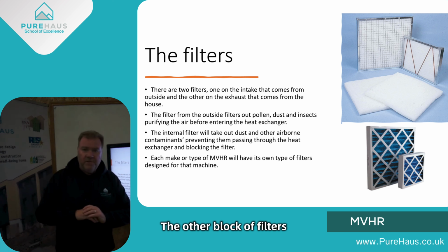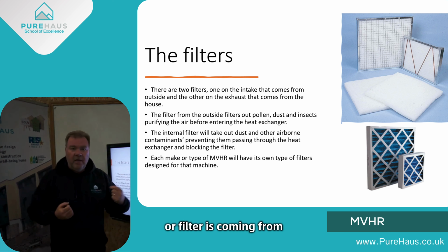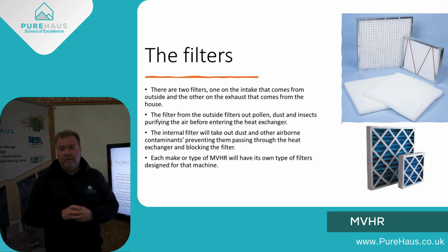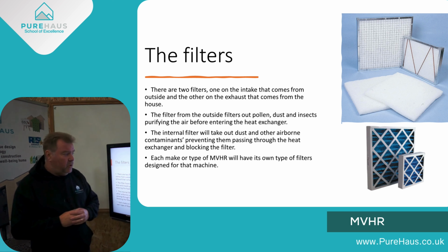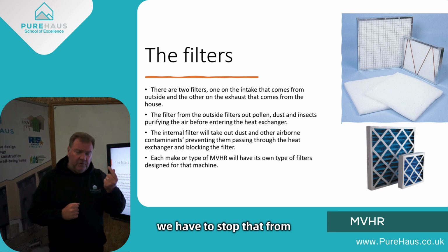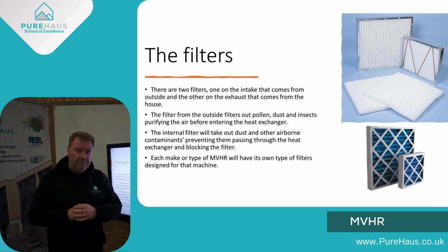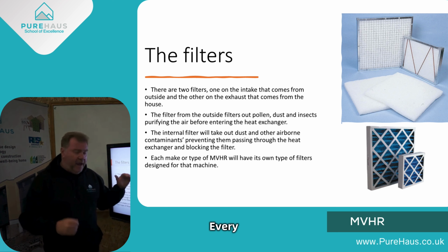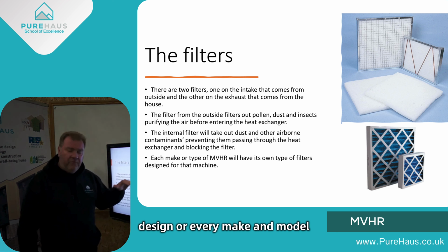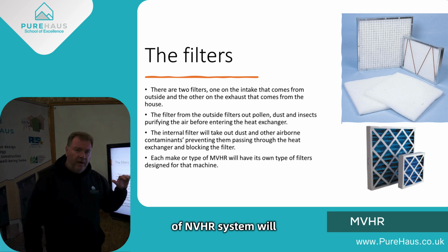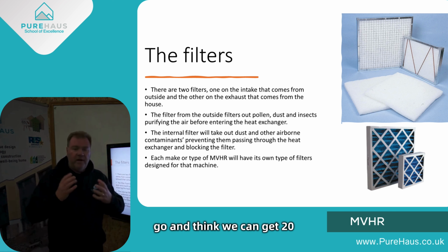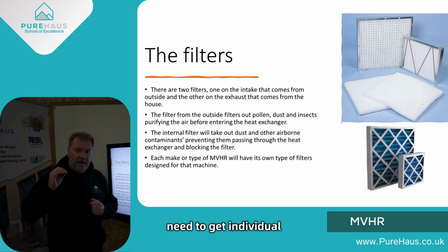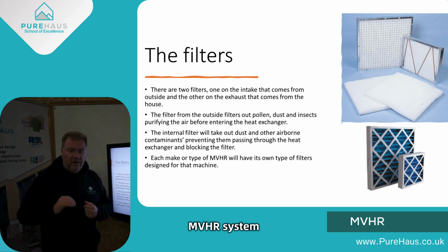The other block of filters is coming from the build, from the living environment. So we have to stop that from going through the heat exchanger. Every make and model of MVHR system will have its own filters. So don't think we can get 20 of one sort. We may need to get individual filters for that particular MVHR system.